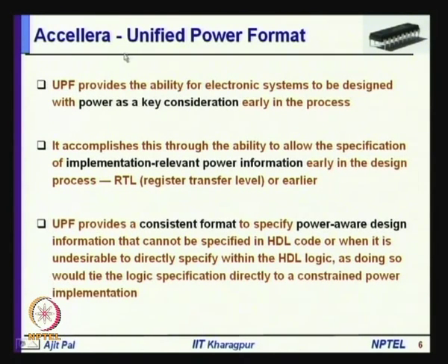Accellera has proposed UPF, a unified power format, which has been widely accepted by industry, and it provides the ability for electronic systems to be designed with power as the key consideration early in the design process, maybe at the RTL level. It accomplishes this by allowing specification of implementation related power information early in the design process. That means, whenever you are doing RTL synthesis using Verilog or VHDL, along with that you will also incorporate your low power intent with the help of UPF.